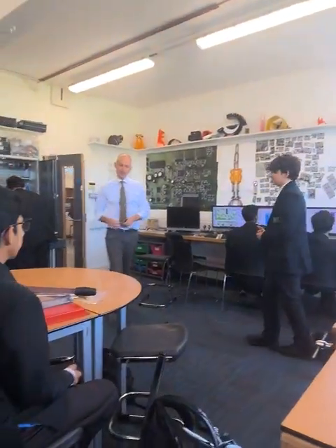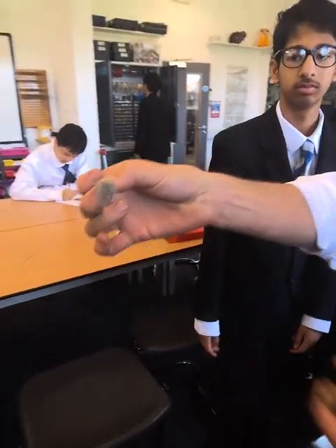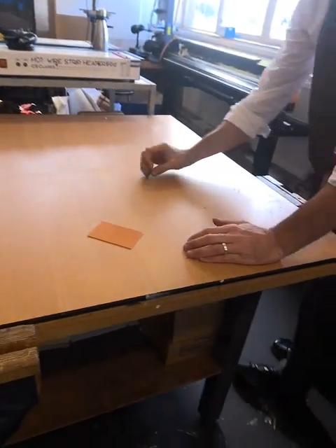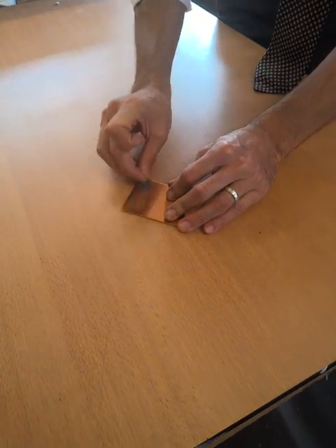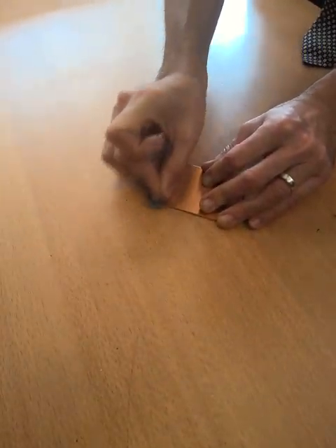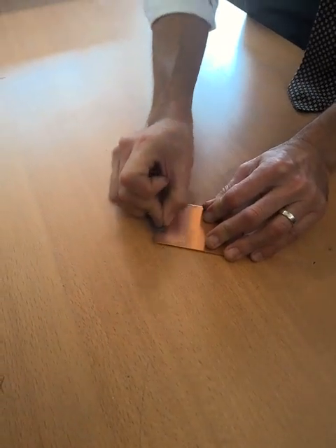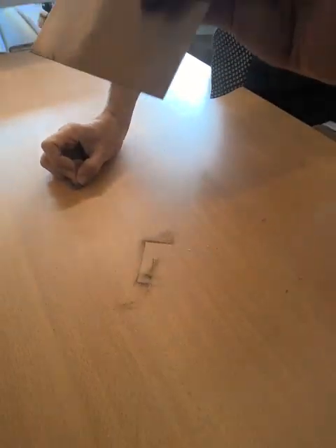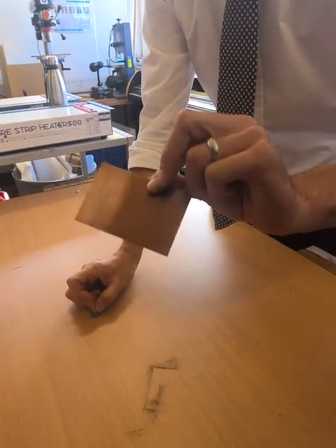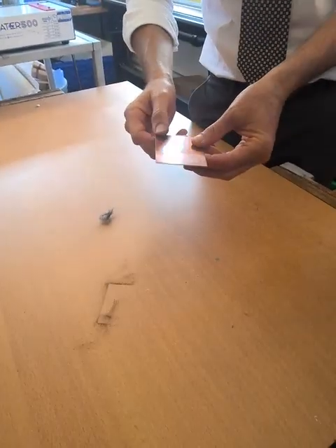Okay, so this is what I was talking about, the wire wool, steel wool. It's called two different things. Can you see it? Now, if you come and look at this, guys, you were saying this is a copper colour, and I was saying, no, it's not a copper colour. And you can see that very well when I start to scratch away and get rid of that photoresist layer. You can see now that that is a bright copper colour, and that's the copper you want to be soldering to. So once you've got rid of all that photoresist, you've got a nice design on here.